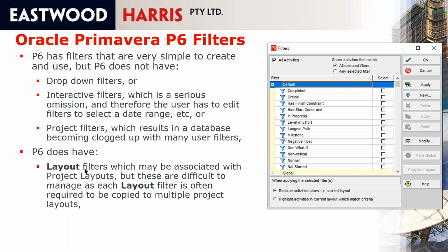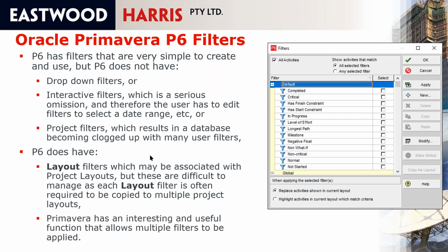It does have layout filters, so you can assign a filter with a layout, but if you've got 10 project layouts and 10 filters, you've got to assign 10 filters to 10 layouts, and therefore that gets a bit of an administration. And it has an interesting function, it allows multiple filters to be applied at the same time. I reckon it's really neat, and that's a significant advantage of Primavera filtering, is that you can select multiple filters and have either all or any apply. But that's one of the advantages of P6.